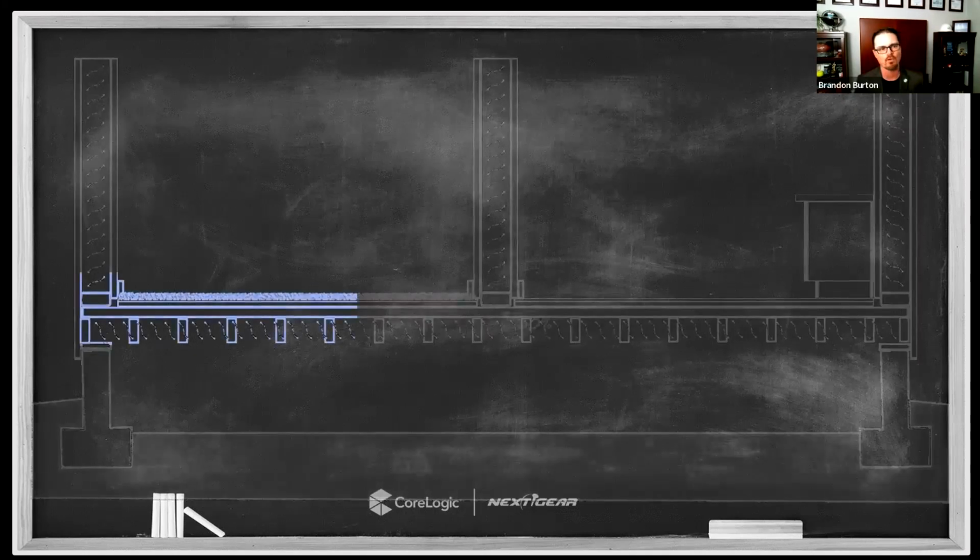To understand that role, let's take a really simple look at an affected area here in this schematic or cross-section of a building. If we had an area here that was affected, maybe a carpeted room in a living room over a crawl space, when we install something like dehumidification, which is removing moisture from air, it's adding some heat energy to the air, so it's producing warm, dry air.